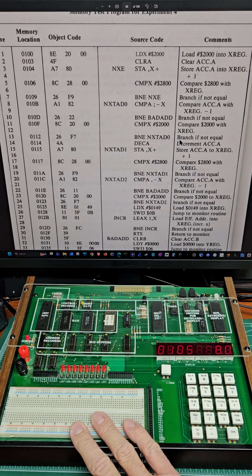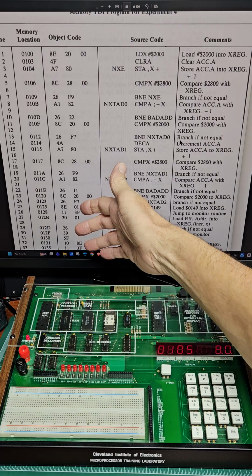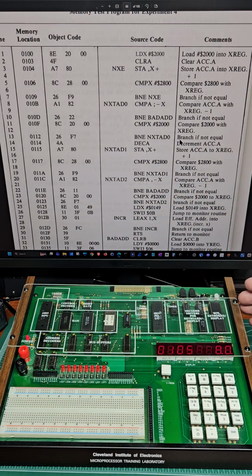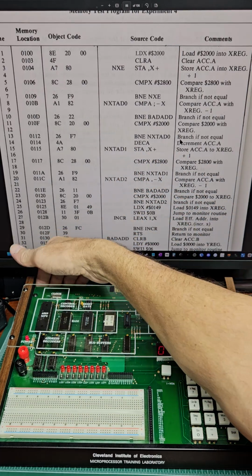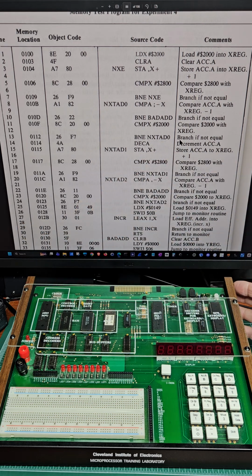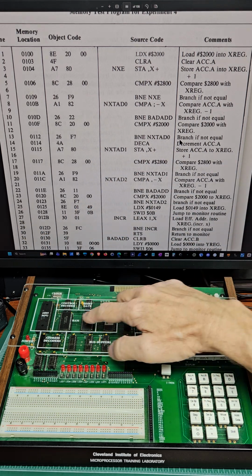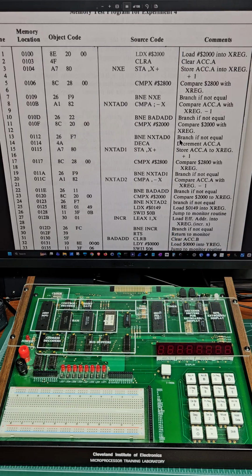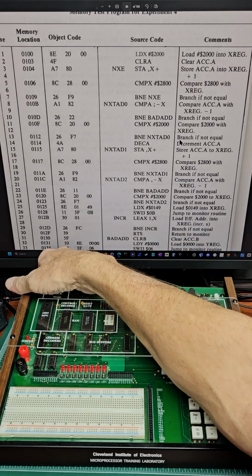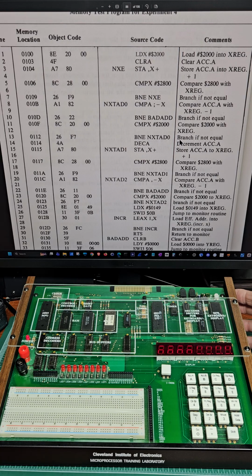Now the issue I have with this is that I type all this in, and I want to do it again later on. And when I turn this off, everything I typed in is gone because it doesn't save, right? Because it just wrote directly to RAM. So I turn it off and turn it back on again, and then look back at address 0100, it's back to 13 again. It lost the data I typed in there. So that was kind of a pain.